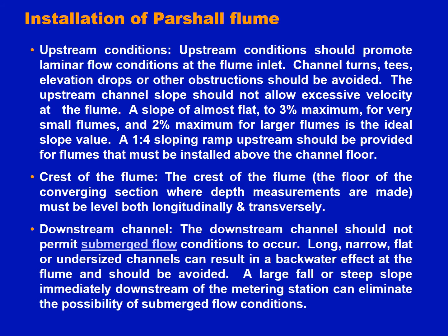Now the crest of the flume. It is very general that the floor of the converging section, where depth measurements are made, should be leveled. Both linearly and sidewise, the crest should be level.